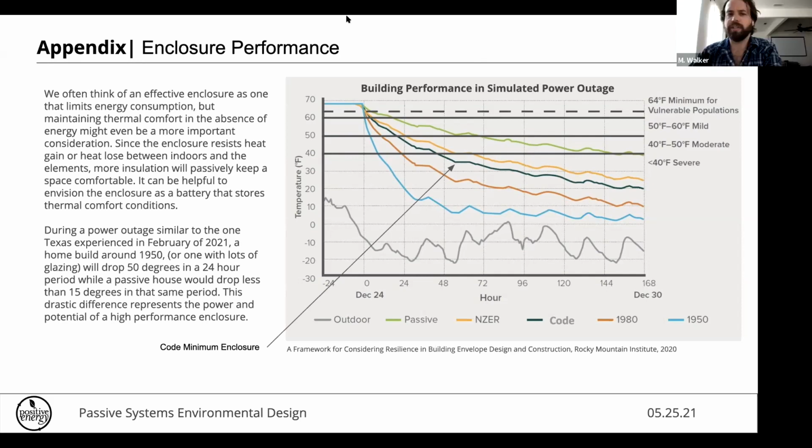Yeah. So there was a quick audience question before we get too far away from windows, because it pertains to windows. The question is, what is the ideal window to wall ratio to improve performance? That's the million dollar question, right? The ideal one is 0%. A refrigerated cooler box would be the most ideal from a pure energy standpoint. One of my professors used to say that the most low energy building you could build is a tent, with no air conditioning. So it's more of a question of give and take. There's no hard and fast number.